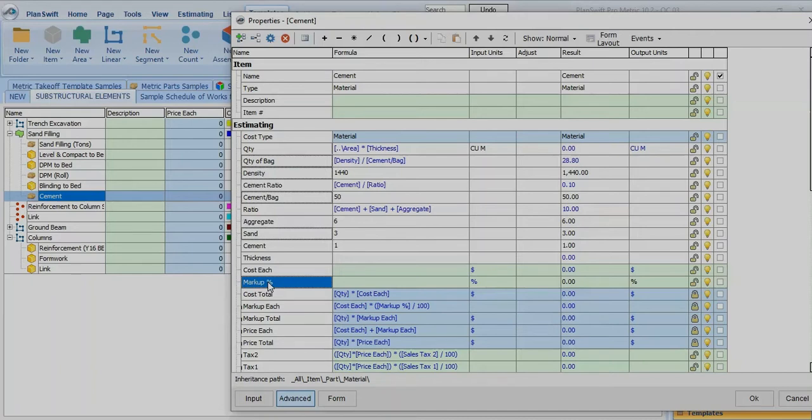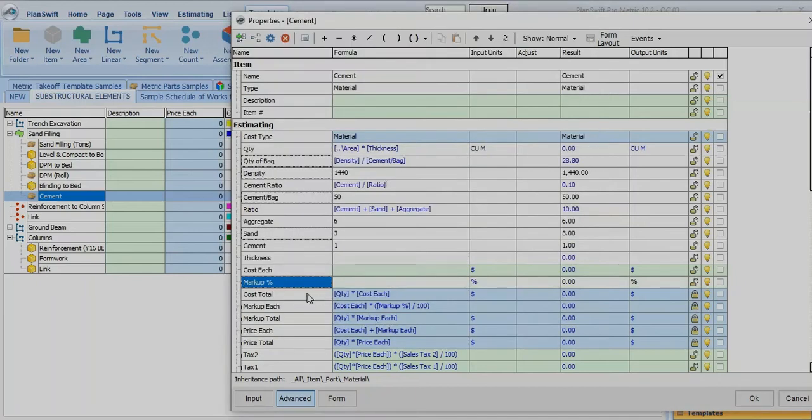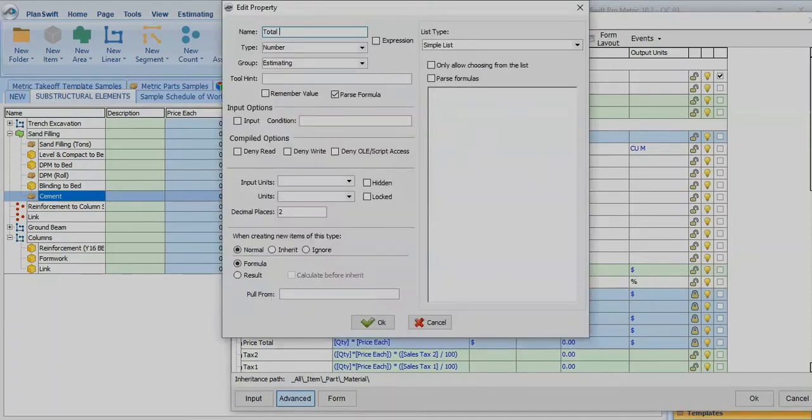So our markup, we have to mark it up by shrinkage. We normally use 50% waste and shrinkage. So let us redefine that one too. Some used to use 40% or 35%, 40%, 1.50. So having done all this, to know the total quantity, let us create total quantity of our cement.